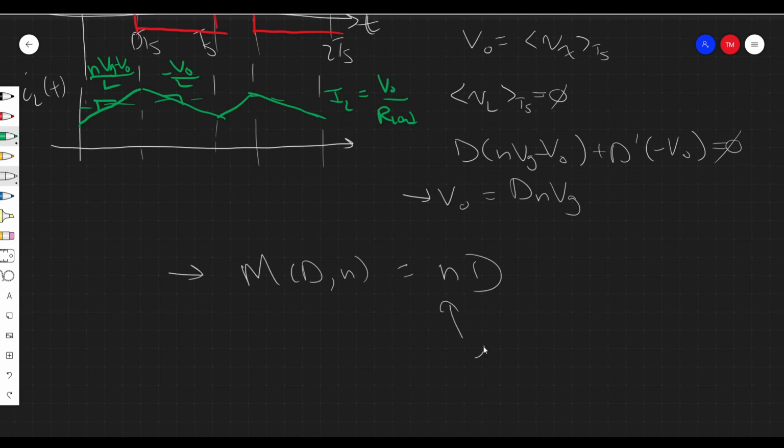And that's kind of the extra power, right? So this is like extra gain. We don't have to rely on duty ratio to control how big the voltage is at the output. Now we have this extra variable. Admittedly, you have to decide what it is beforehand, but you can control it with N, right? You can choose, okay, I want the turns ratio to be 1,000 or 20 or whatever number you want. And again, we could fit in a half bridge on the input side. We could fit in a full bridge rectifier on the output side, and it would be a little bit different, but it would look pretty much the same, right? So if you use a half bridge, you just have to have a factor of 1/2 added to this because the input voltage is basically divided by 2. But other than that, it's pretty much the same.